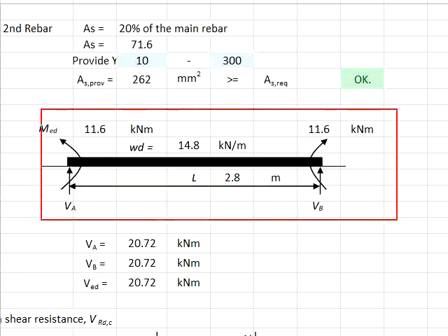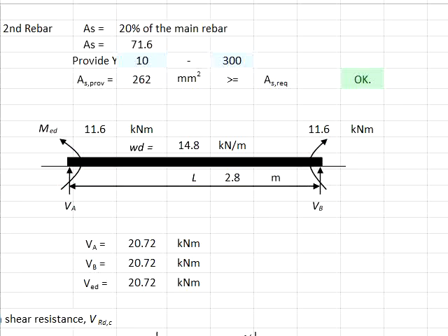Use the principles of static equilibrium. Taking the point here, ΣFx, ΣFy, and ΣM equal to 0. You are able to determine the vertical force B here. Do the same for the support here.